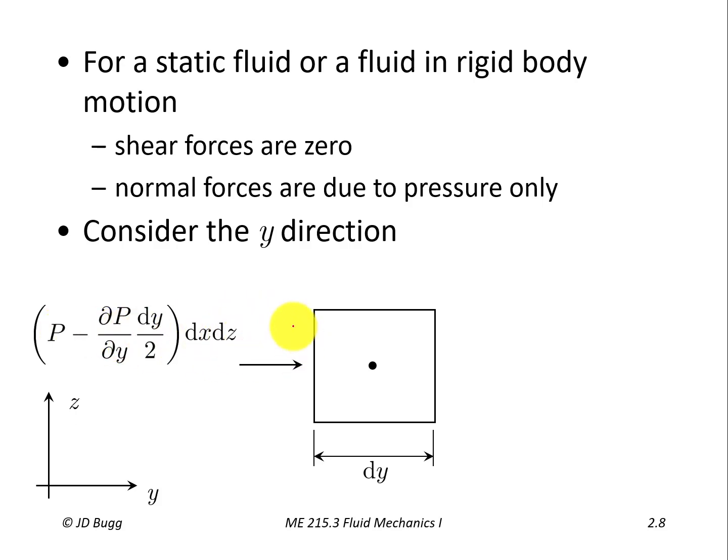So the last thing we need to do here is give this the right direction, and the direction of this force is the positive j hat direction. So I'm just multiplying this scalar quantity by a unit vector in the positive j hat direction, because the fluid out here is pushing in that direction, the positive y direction. So that expression is the surface force, but only on one of the 6 faces of this cube.